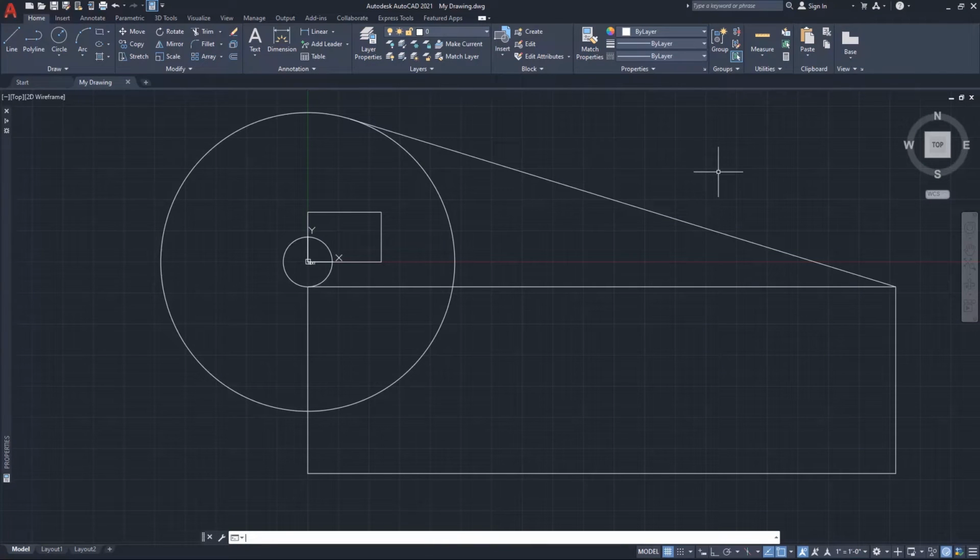Before we create our first dimension, let's take the opportunity to explore how layers are used to organize our various drawing elements. In the Home tab of the ribbon and to the right of the Annotation panel is the Layers panel. A comfortable way to think of layers is to think of each individual layer as an individual sheet of trace paper or vellum, where each individual sheet contains drawing-specific types of items.